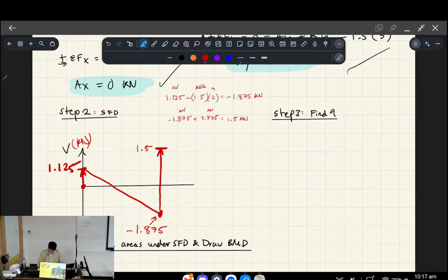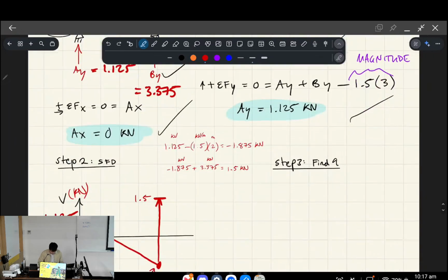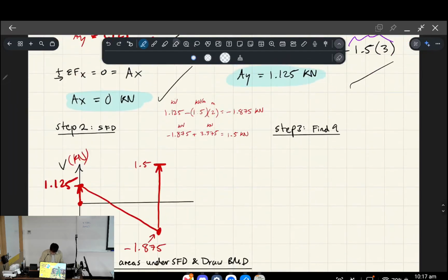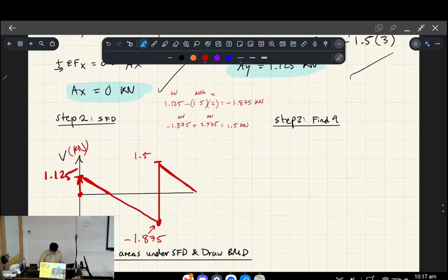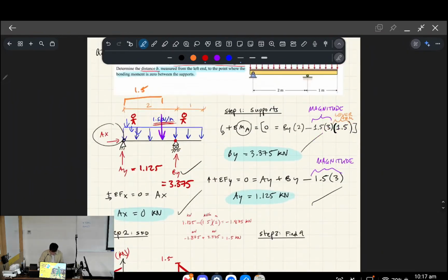Okay, the next thing that happens is as the man is walking on this portion of the beam instead now, we've got the same uniformly distributed load, but it instead acts over 1 meter. Okay, so we've got the same slope. I kind of drew this not to the right scale. Give me one sec. Okay, maybe like that or something. The idea is I'm trying to redraw this line's slope. Okay. And then essentially it reaches 0. Okay, and the way that you can verify that is this was 1 meter.